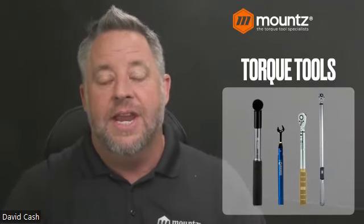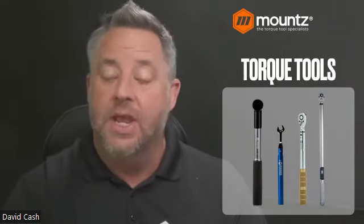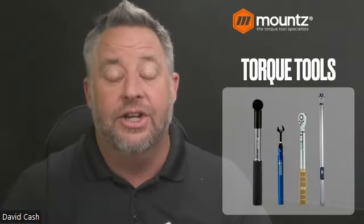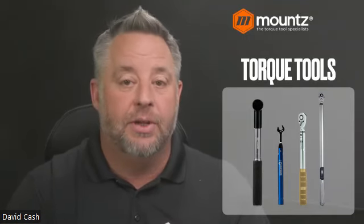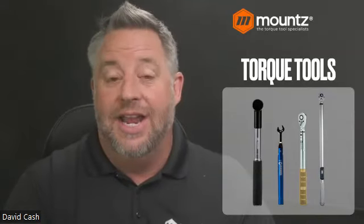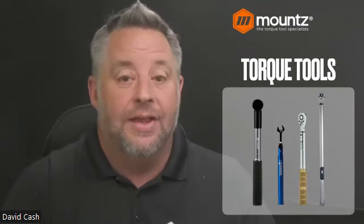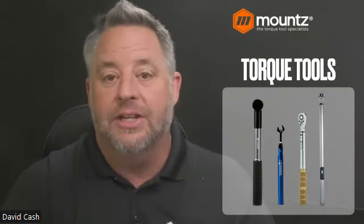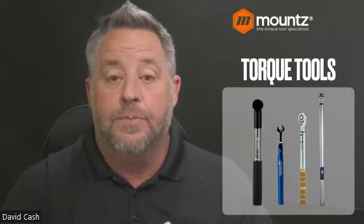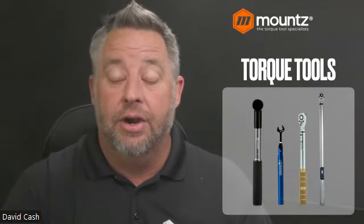And so the click wrench itself is a signaling type of tool. If the operator pulls past the signal, they are adding additional torque to the actual application. If they double click or triple click, and in some cases, we're adding almost double the amount of torque that the operator is trying to achieve by doing that. So the tool itself is very dependent on the operator.